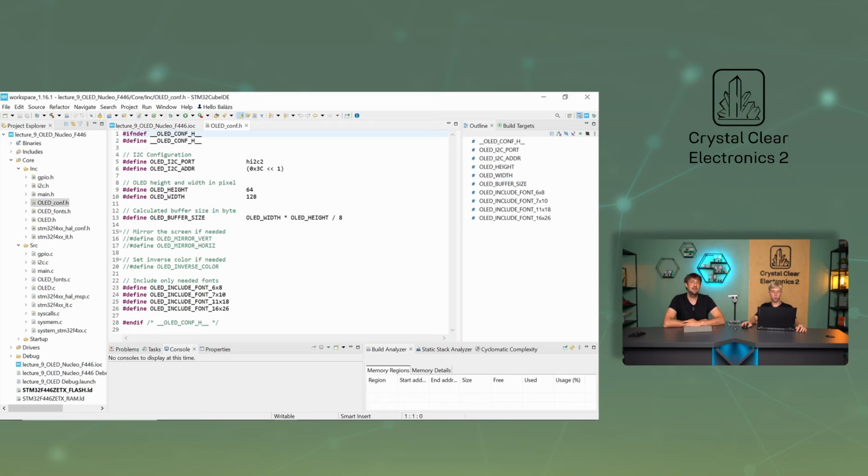We can control the display by sending commands over the I2C bus using the familiar HAL I2C MemWrite function. This function has 2 hardware-dependent parameters. The I2C handle type def, which is a pointer to the configured I2C structure, and a 16-bit address, which is the address of the target device. In order to make our code modular, we have defined these 2 parameters with the following 2 macros.